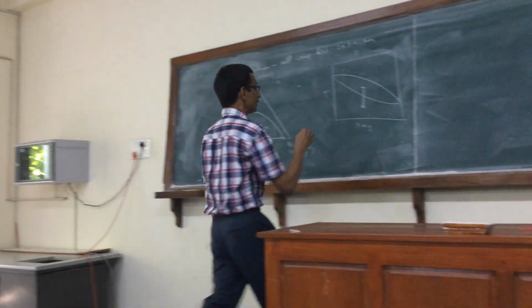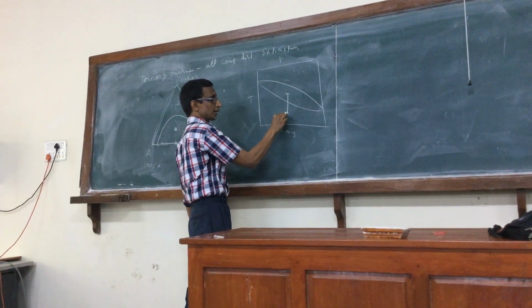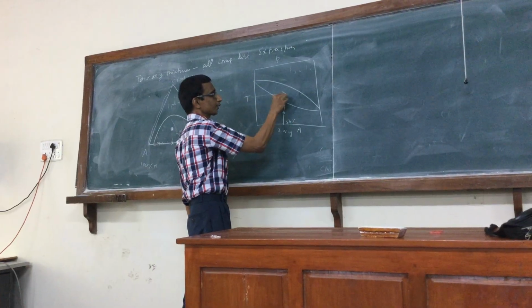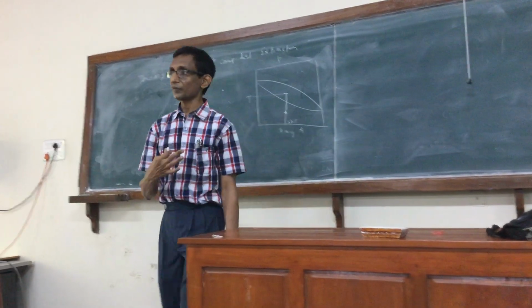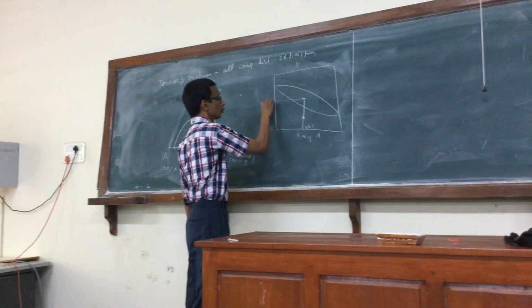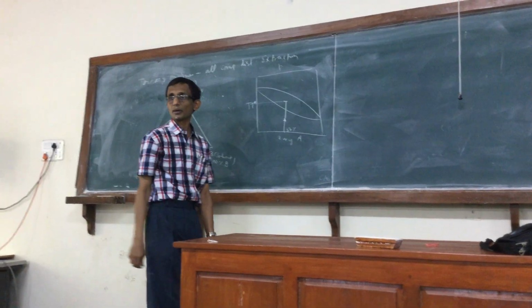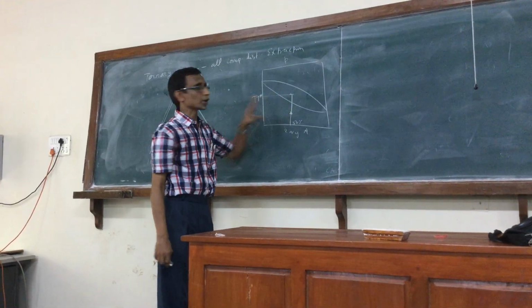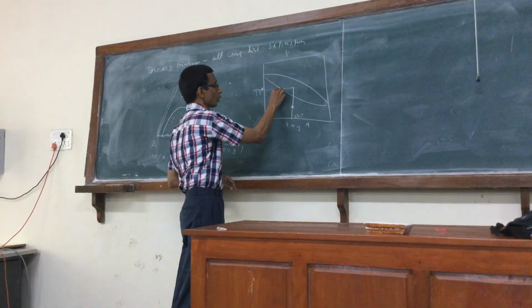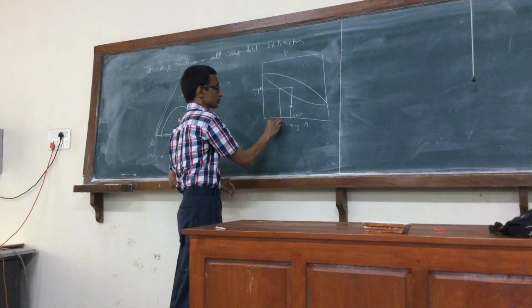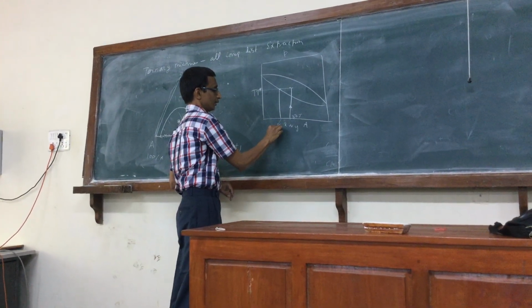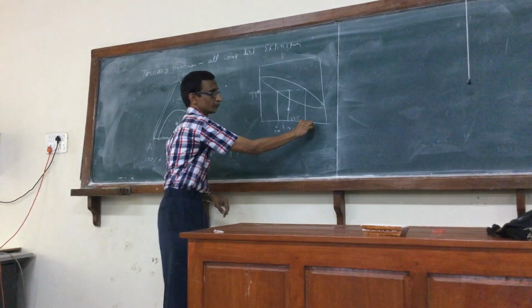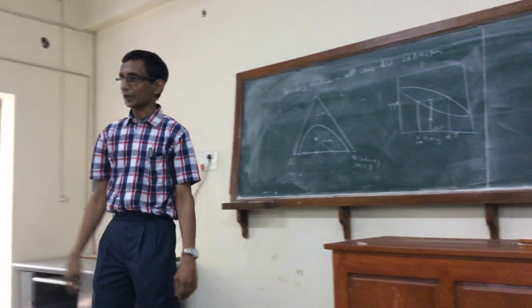So if I see that I have heated the mixture initially containing, let's say, 50% air, and I have heated it to this temperature, so I specify that only to you. So I know that now, let's say I have reached T star of this overall composition, nothing is added or removed. So clearly now it is in the two-phase region. So this will be the composition X, and this will be the Y star of the vapor. That's very easy to do.